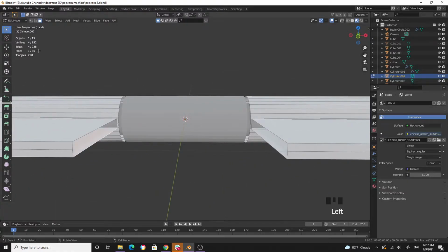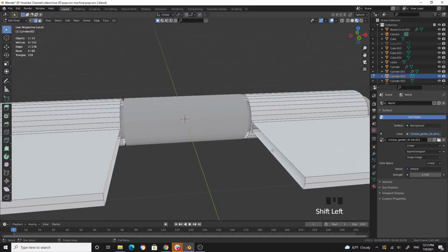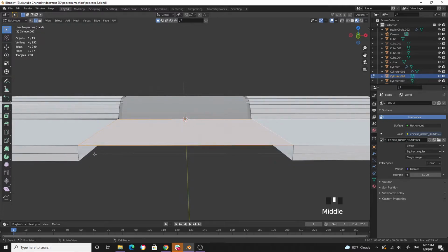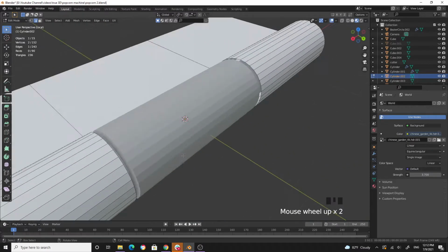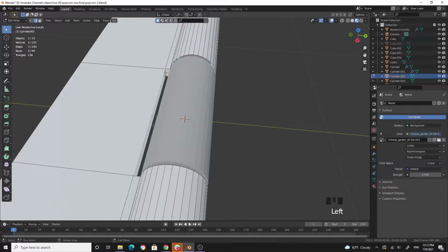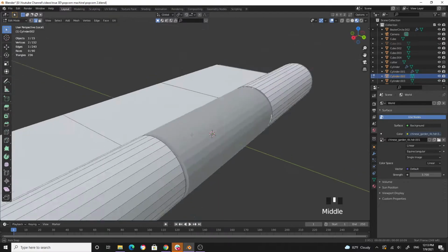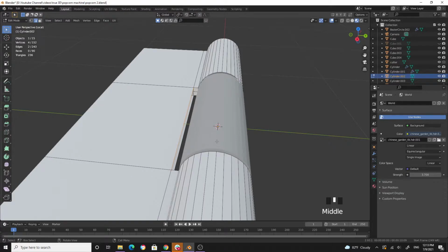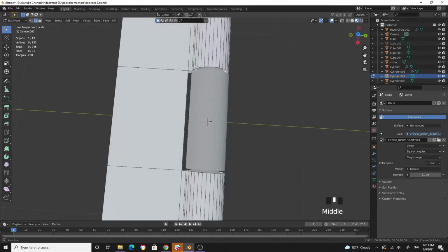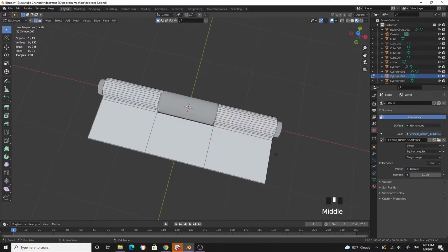Now what I do is select this edge and this edge, connect, bottom edge, fill, right? This one, fill, this one and fill. Alright, so the same thing you can do here. If you select this, press period key and select the other face, edge, and then fill. Alright,